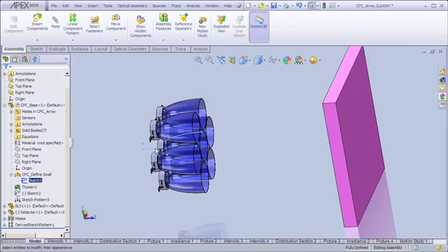I do not need to go and create new geometry every time I want to use a CPC in a design. I simply have a CPC geometry stored on my computer, and I reuse it anytime, taking clear advantage of the document reuse capabilities of the SOLIDWORKS engine.